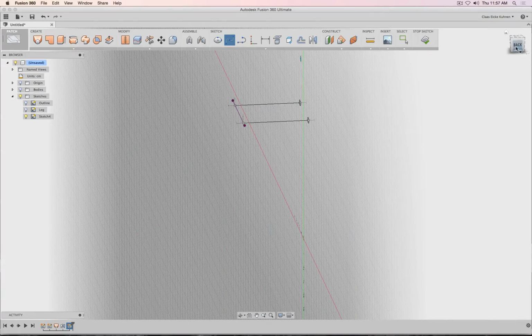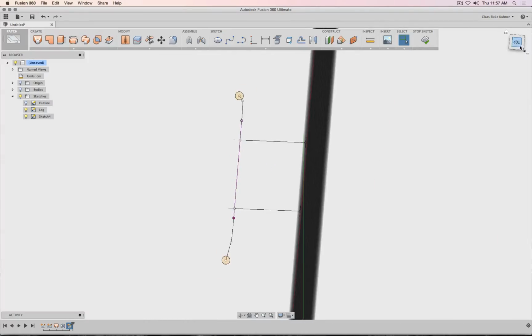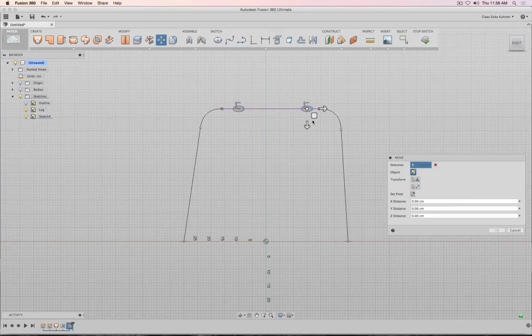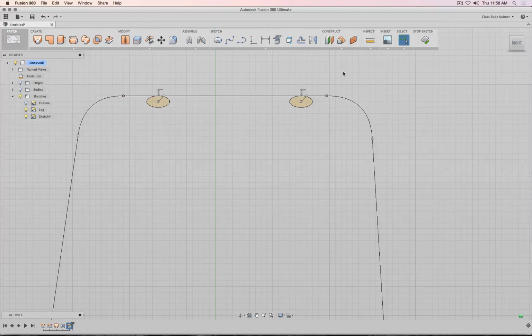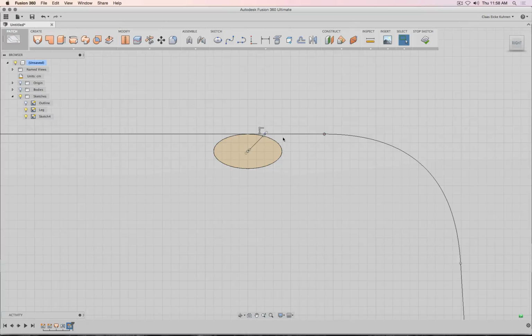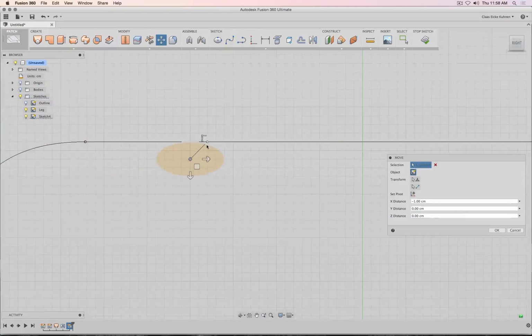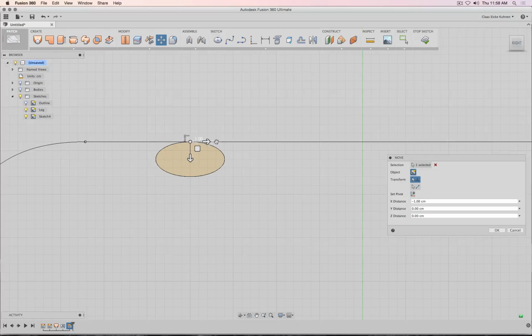I can hide this for the moment, and you see there now this red line, and there are point constraints, so this spline will always rest on this line. Pretty nice. Good. Then I could select these two rings and just let them move down maybe by a centimeter. Okay. Maybe from this view we can click this point and correct it. Same here. Okay, so this point move to there. Okay.